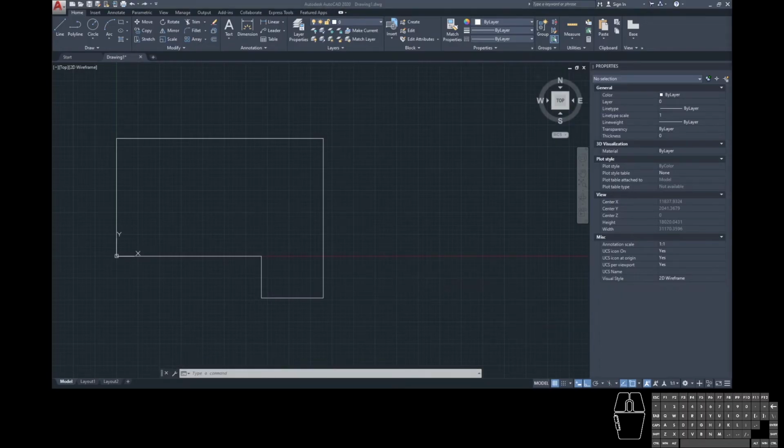We're now going to run through the remaining tools that you are going to be using during your AutoCAD process. First off is the Move tool. Move tool can be found in the ribbon, Home tab, Modify panel. First one, top left, Move. You can also engage the Move tool by typing Move or by using the shortcut, which is M.